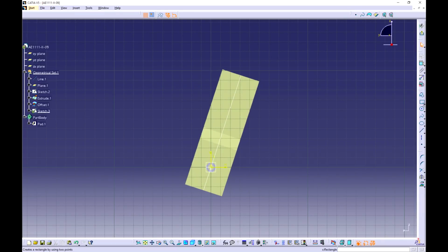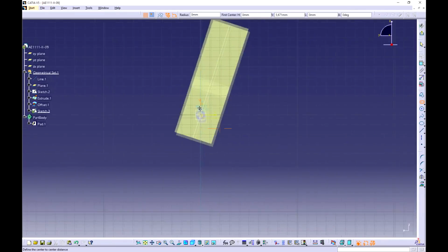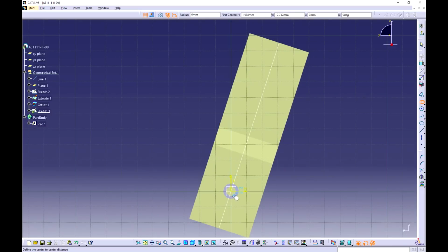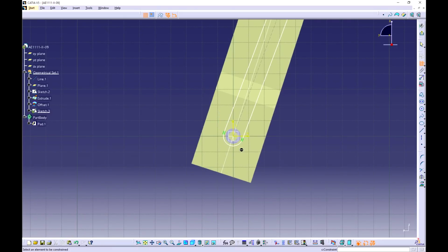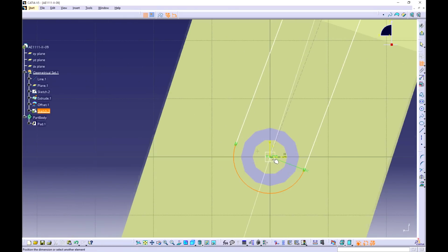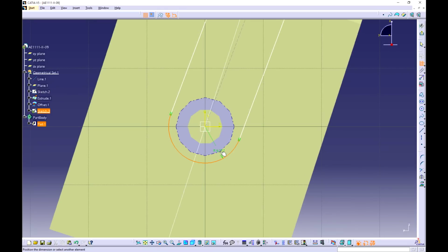And now we use the elongated hole tool from the rectangle stuff. Place the first point in the origin, this, 0, 0, and blue indication, and pull it up straight here. And make an elongated hole. The constraint down here we can delete and select constraint tool, select our lower arc, and our outer circle of our stick and make constants.